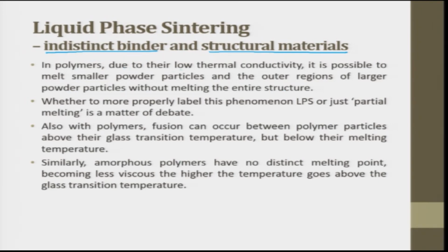So, in polymers, due to their low thermal conductivity, they do not absorb heat, so it is possible to melt smaller powder particles and the outer region of larger powder particles without melting the entire structure. That is nothing but a distinct binder and structural material. Whether to more properly label this phenomenon as LPS or just partial melting is a matter of debate.